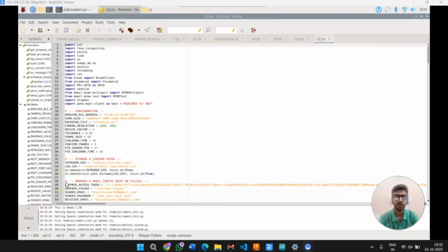And before looking at all the libraries and the things that we have installed, I need to tell that I have worked on this code primarily in the Python virtual environment that I have created, and not on the global environment of the Raspberry Pi terminal, because the libraries were too heavy and not supported by the latest versions such as Trixie. So I have set up my Raspberry Pi 4 with the older versions, and then created a Python environment, and I am using all these codes on that environment because on the latest environment it was too heavy and I was getting so many errors.